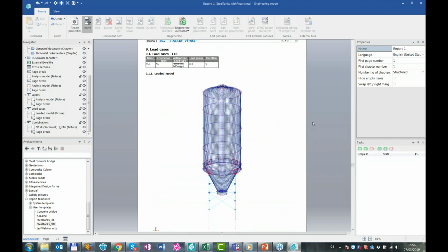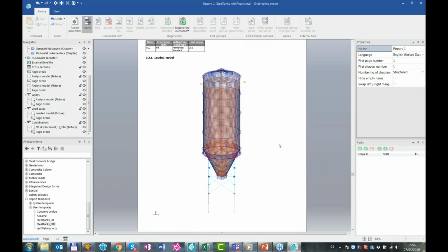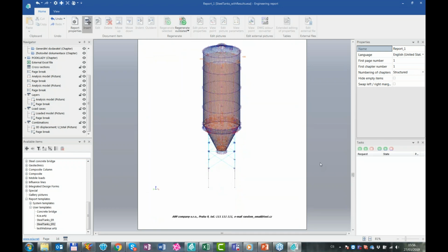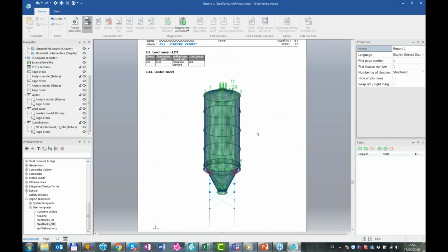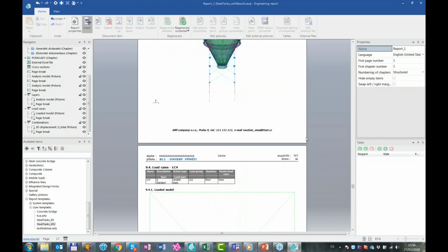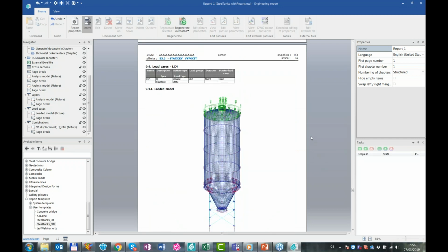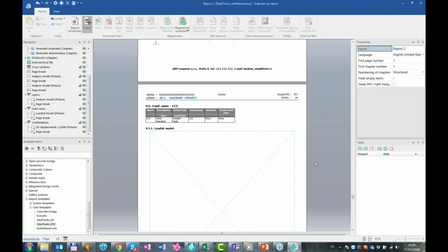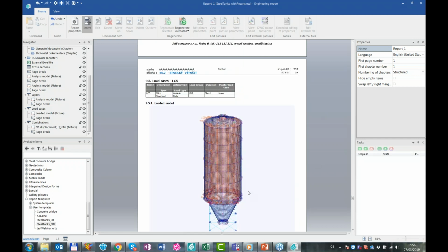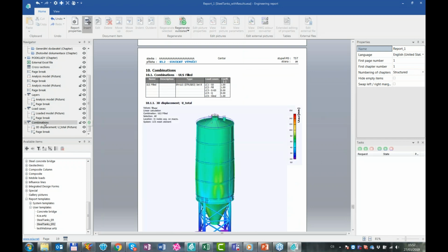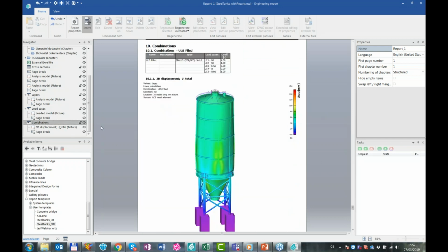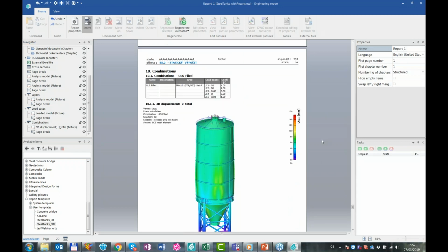For the load cases it works the same. Here I have the self weight. Okay, there is nothing drawn here, but here for the filling I can see the load being generated by the filling, also by the other dead load, by the imposed load on roof, and also by the wind. What I can also do, I can indent result images under, let's say, this time combinations.